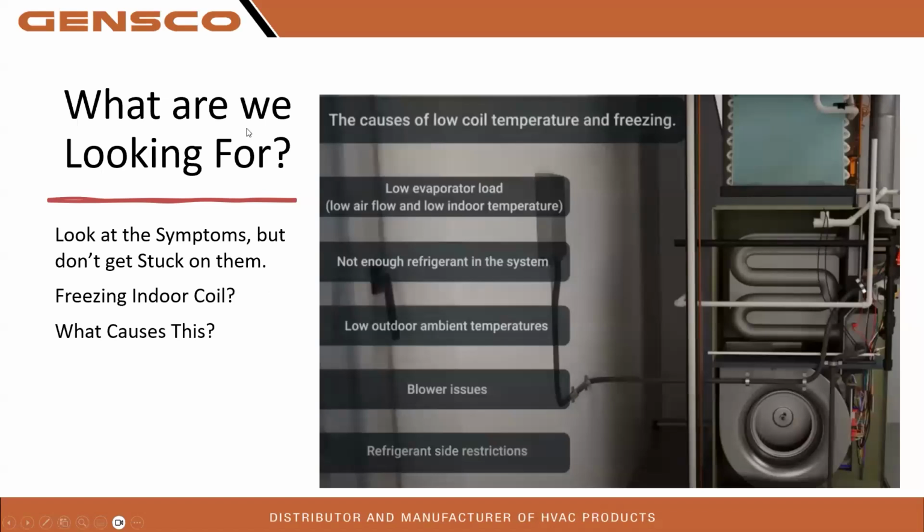So if you look at some symptoms with a freezing indoor coil, what's causing that? Let's not get stuck on it, but we have to understand, well, freezing coil means we have lack of refrigerant flow or lack of airflow. Simple as that. Plain and simple. We need to figure out what is going on there. If we have a low evaporator load, maybe the indoor airflow is just far too cold. Maybe it's 75 degrees upstairs, but we've got a 20 by 20 return grill in that 65-degree basement. And because of that, we've got a low evaporator load. We have no way of absorbing heat into that coil because there's really not much heat to do it.